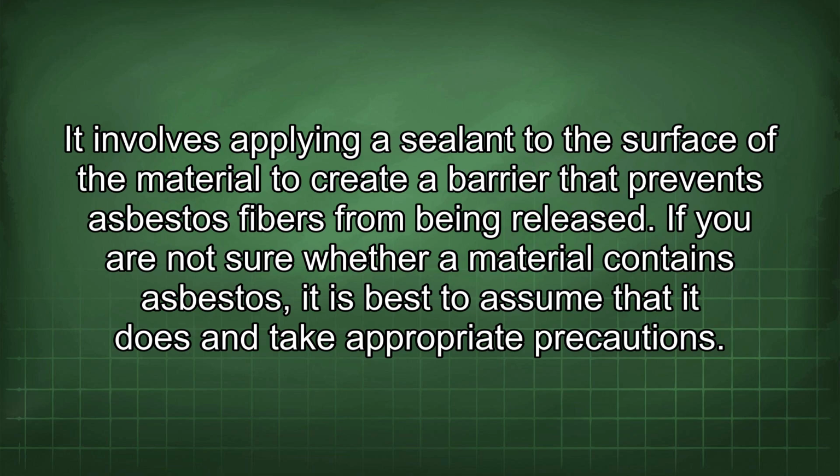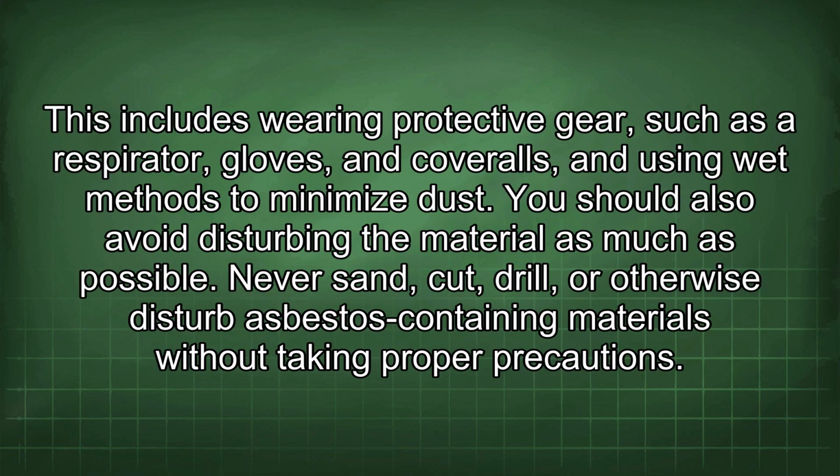If you are not sure whether a material contains asbestos, it is best to assume that it does and take appropriate precautions. This includes wearing protective gear such as a respirator, gloves, and coveralls, and using wet methods to minimize dust. You should also avoid disturbing the material as much as possible.